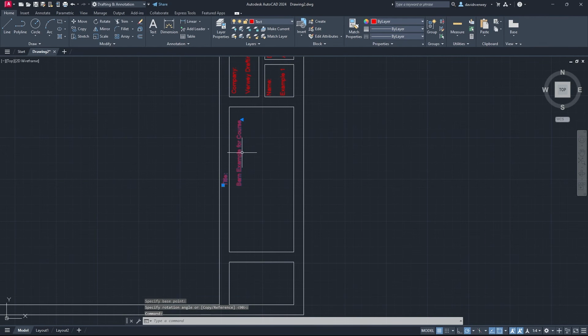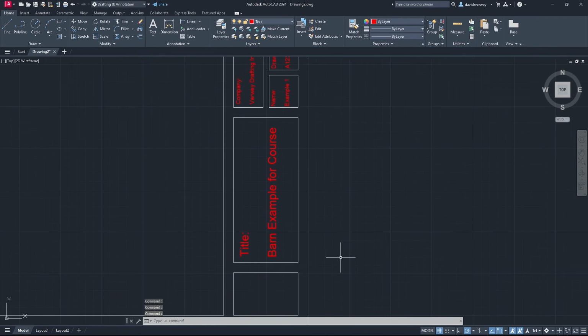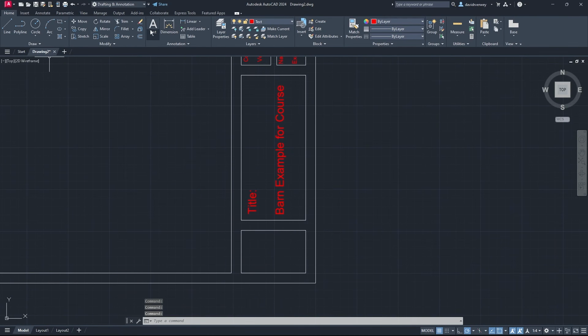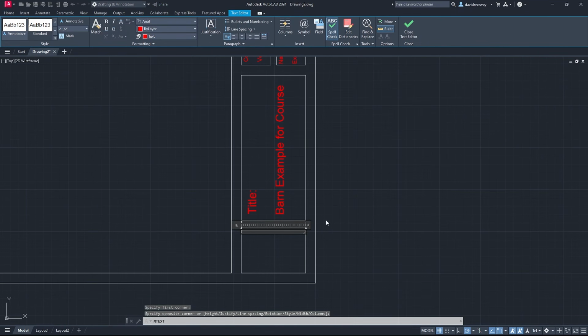I'm going to rotate it, pull it down, and fix it. I might actually scale this larger. I'm going to scale it a little larger. I encourage you to do the same, because usually they are larger. Title usually is larger. And then down here, let's just put the date. Usually title blocks are a lot more complex than this, but this is, again, a basic title block.